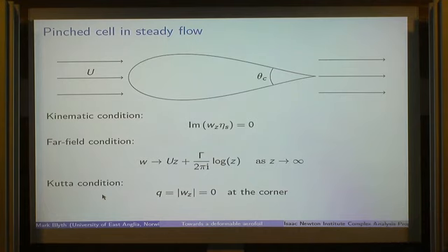Do you have any angle of attack or anything? Well, that's going to be set naturally by the shape, because I don't know the shape at the beginning. Yeah, so I'm going to fix theta c, and the angle of attack is effectively going to come out in the solution.